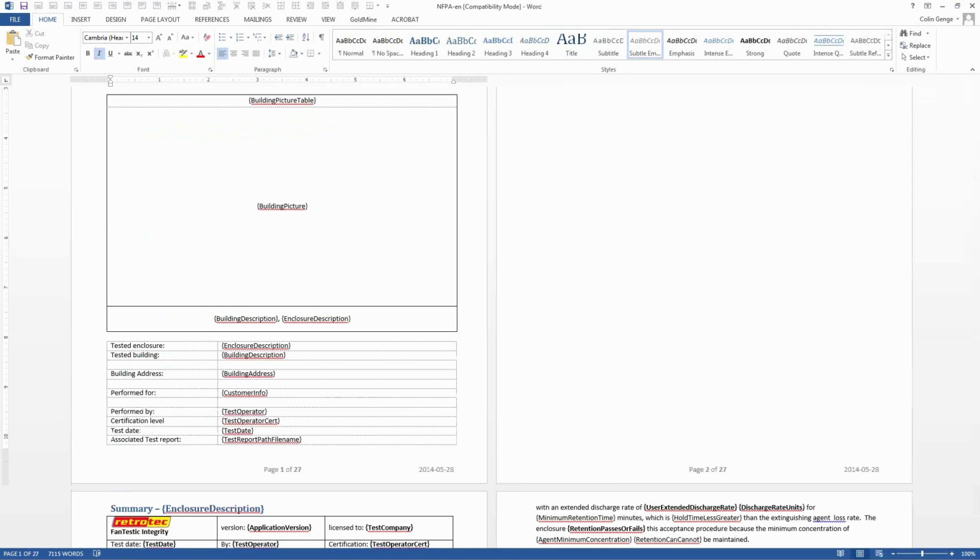So someone was asking, do we have extra liability if we use calculations for peak pressure that are not actually included in NFPA 2012? NFPA 2012 doesn't actually provide peak pressure formulas. It says you must do a peak pressure evaluation and leaves it up to you as to how you do that peak pressure evaluation.